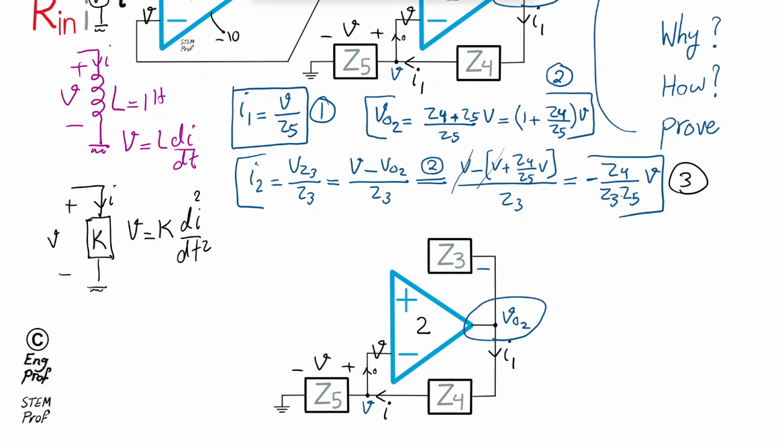then this portion of circuit looks exactly like a negative impedance converter, NIC. So the circuit that I'm showing is actually a more capable circuit than a simple NIC. This is what the NIC is. When you apply voltage here, between that node and ground, then the sensed input impedance, Z in or R in, is exactly minus Z4 divided by Z3 over the other way.